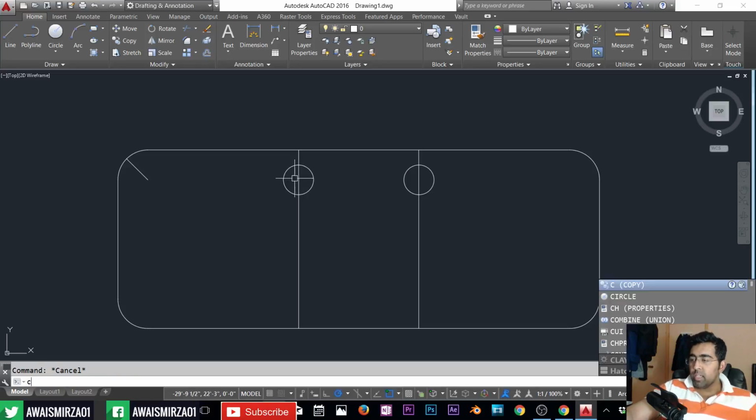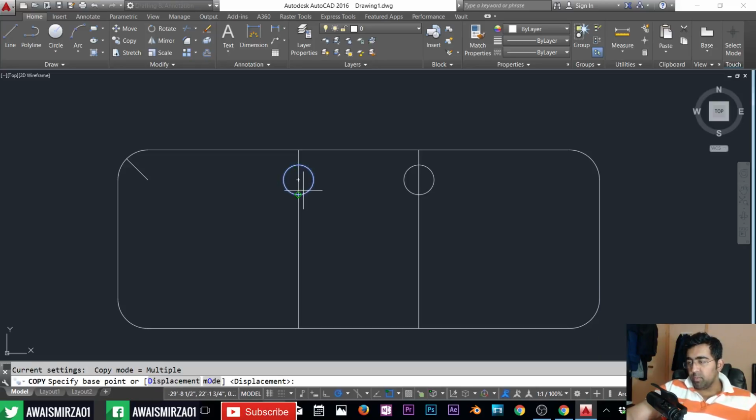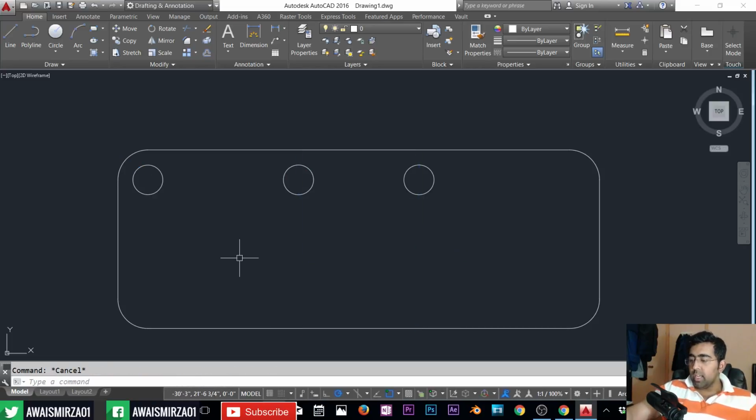So now I can copy one of the circles from the midpoint, and we can drop it there, right? Now let's get rid of this line. We don't need that anymore, and we don't need these anymore, right? I'm going to mirror this with the mirror command. Select this circle, select this midpoint, and drop it there. Okay, select these two circles, select this midpoint, and drop them there, right? I think the foundation is a bit bigger, but for now that's fine.